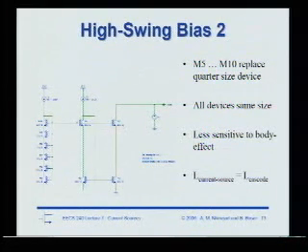Yes. So in all these designs, if we go to the short channel regime, the sizes that we have all derived, 1/4 exactly, none of these will be exact. So how do we go about designing these things? Because we have to decide what the overdrive voltage will be, how the VT will change with channel length, and that's why you make good money as an analog circuit designer. It's not that simple. You can't just take the textbook solution and use it.